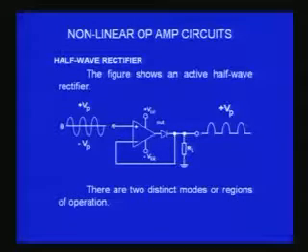Now, when the voltage increases from a very low value, you find initially that the diode can be in open condition, that means it is not forward biased. Therefore there is no feedback loop from this point to the minus input, because this is open. It is equivalent to almost connecting this point to the ground.